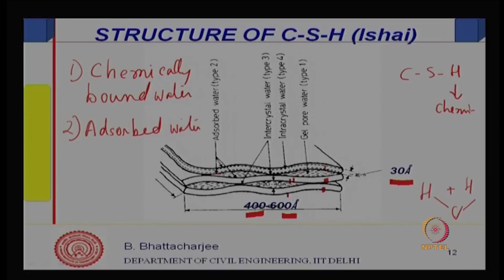And besides that, of course, you can have capillary water, which is taken up by suction, capillary suction. If you have larger size pores, some mesopores, not very small pores, fine particles, of course the adsorbed layer would be there, but in slightly larger size pores, water can penetrate by capillary suction. So, the third type of water held is capillary water,